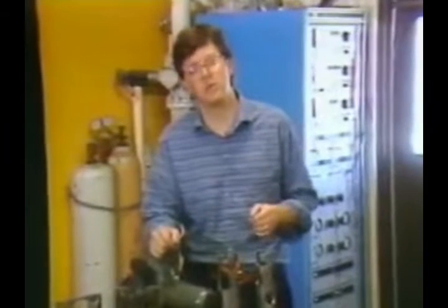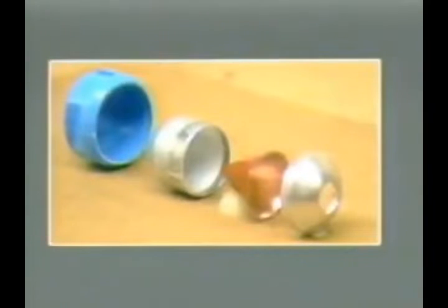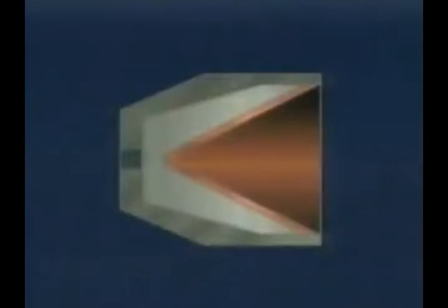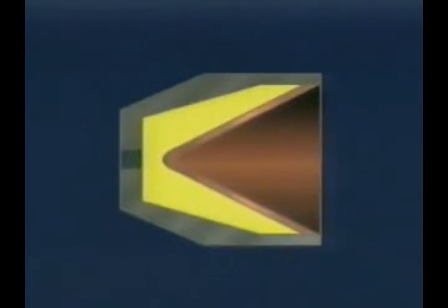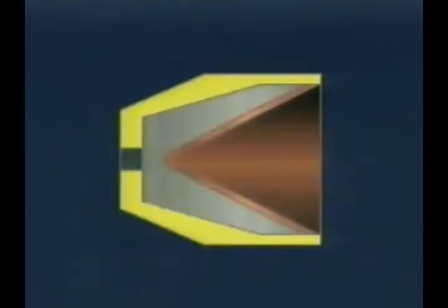Let's look at how a shape charge functions. The shaped charge, or jet perforator, first came into use in the oil field in the 1950s, following the development of explosive technology during the Second World War. The four important components of the shaped charge are the conical metallic liner, the main explosive charge, the primer explosive, and the case that encloses the charge. Simply stated, the firing is electrically initiated by the detonator or blasting cap via the detonating cord, which in turn sets off the main charge.